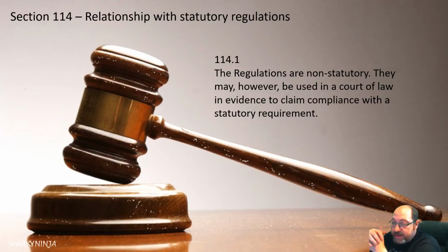All right. It then says, I'm back in 114.1 now, in the paragraph below, for a supply in accordance with the ESQCR, it should be deemed that the connection with Earth of the neutral of the supply is permanent. So it's not temporary, it's not bolted, it's not screwed, it's a permanent connection. Outside England, Scotland, Wales and Northern Ireland, confirmation shall be sought from the distributor that the supply conforms to the requirements corresponding to those of the ESQCR. Okay.